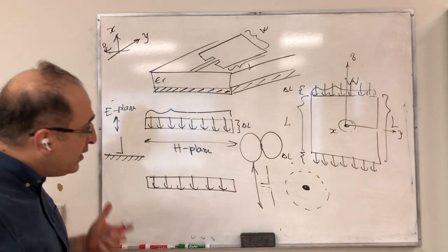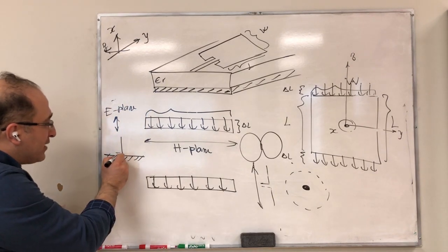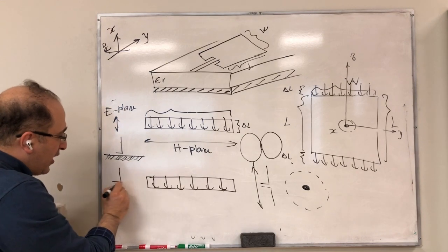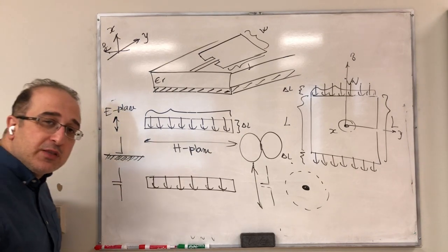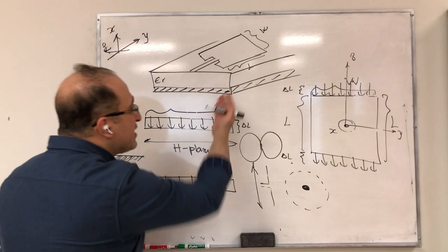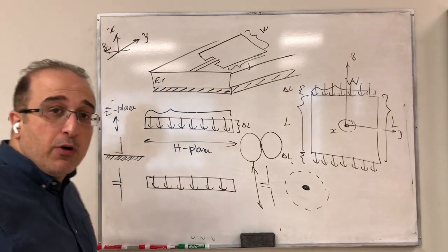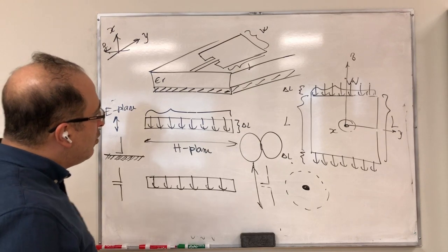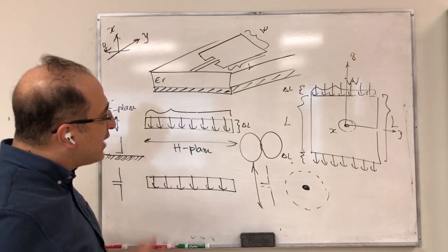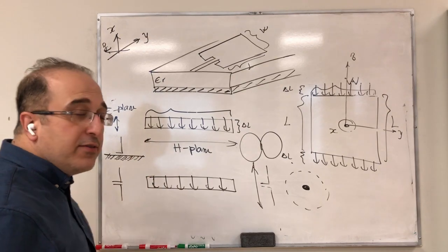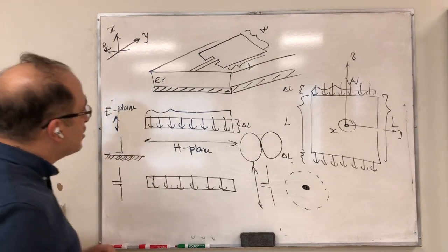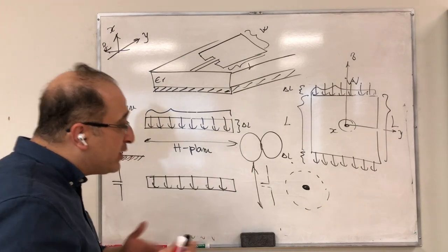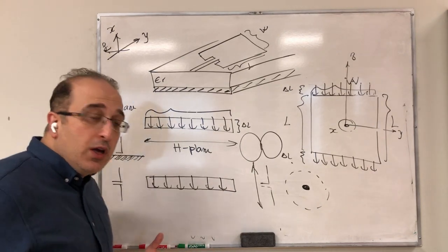If you remember, in the monopole antenna, because we had a ground plane here, we got higher directivity compared to its corresponding dipole antenna. And this ground plane plays a similar role for us. It increases the achievable directivity. So that's one way you can estimate the directivity of your structure: you have a two-element antenna array, so you could potentially get a factor of 2 because of that.